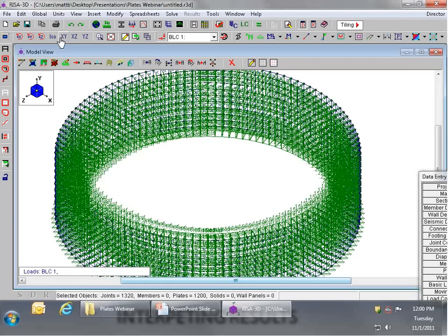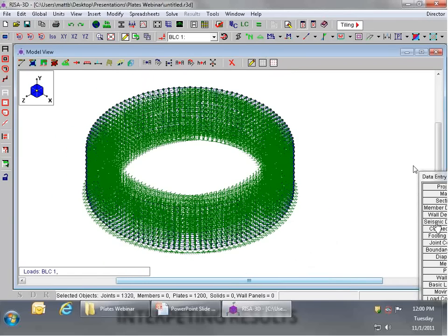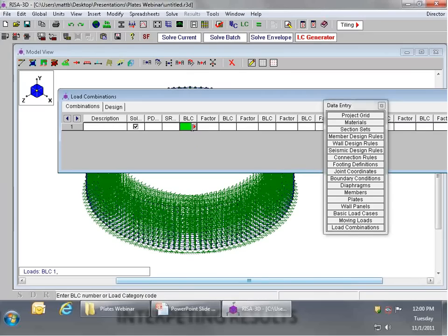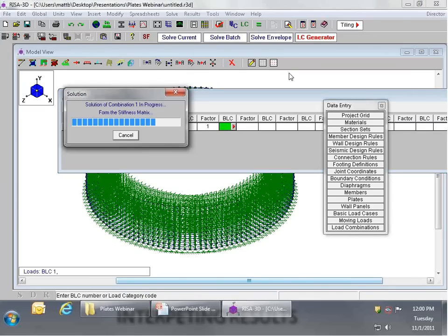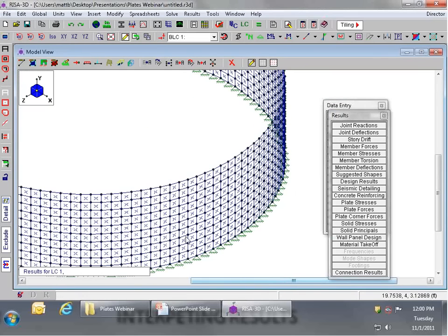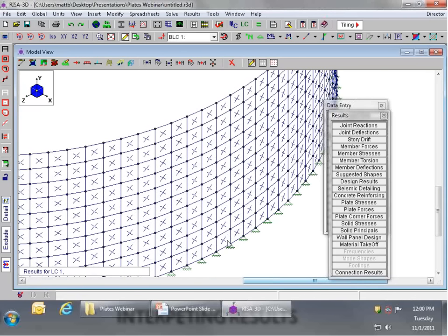So now I have this stepping load that's occurring in here, and I just added those loads to basic load case 1, so we'll just solve basic load case 1 with a factor of 1. And take a look at what our results are. And in here, let's say that I wanted to design this tank for, say, rebar that's running along its circumference. And so what we're going to care about is what would be known as the hoop stress. Well, in this case, I can't really get a very good stress reported out of this. My stress results all typically relate to things like bending or a von Mises stress, which isn't going to be as directional as hoop stress.